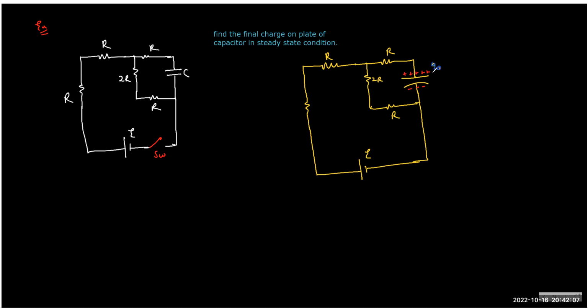Yes. So in steady state, nothing can go through the path in which the capacitor is present. The path in which C is present, no current can go through that path, because that is called the steady state condition. If we have achieved the steady state, then the capacitor will not allow any current to flow. Then what we do is look for the alternative path.